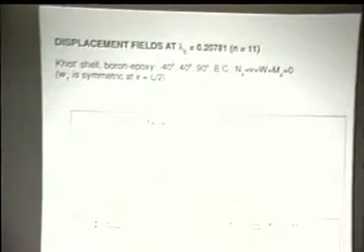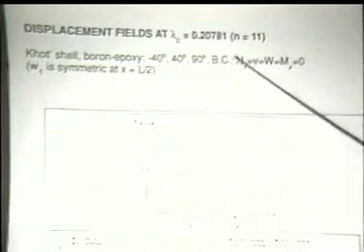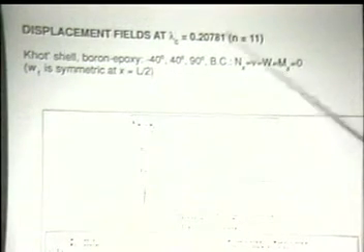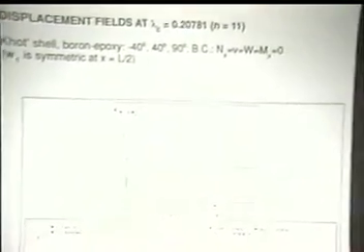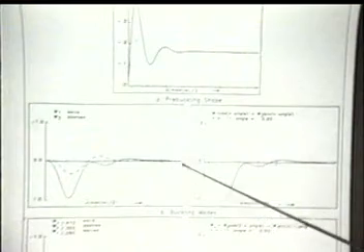So my comment about using subspace iteration: you can pick up practically simultaneous modes. The difference between the two is only in the fifth digit. This naturally looks precisely the same. This very much looks the same, right? Only here, if you look very carefully, you will see that the other one was anti-symmetric, this is symmetric.